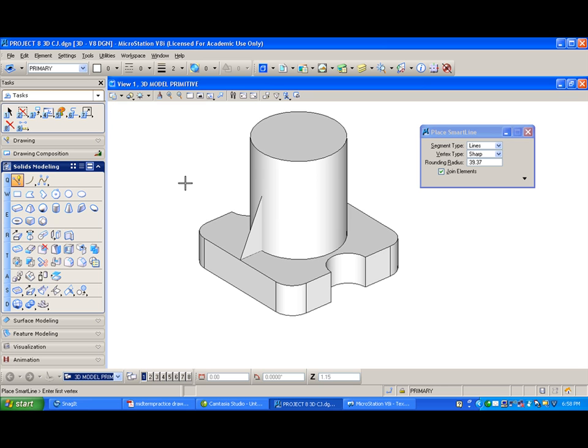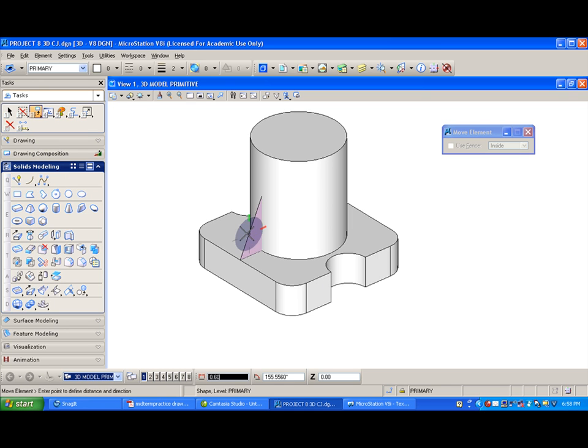So it's just a two-dimensional shape. It's centered on that piece, and the thickness is 0.15. So I want to move this half of 0.15 either this way or this way. So I'm going to take my move tool. I'm going to grab this edge, hit T for top so it rotates my compass, and I'm just going to move this 0.15 divided by 2, or 0.08.